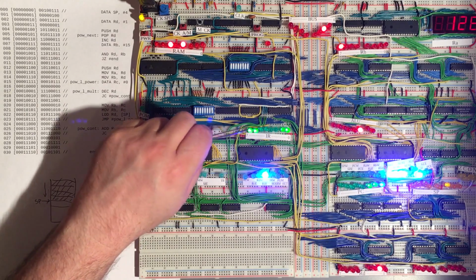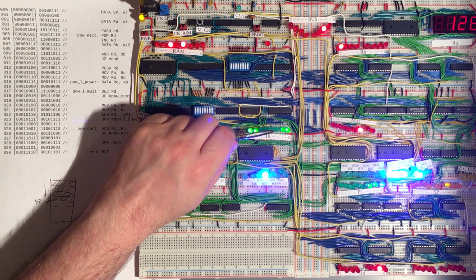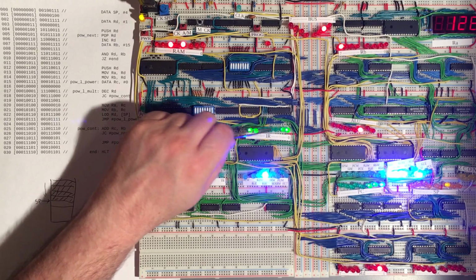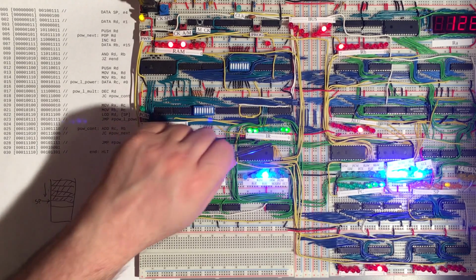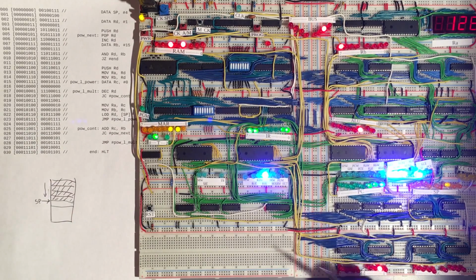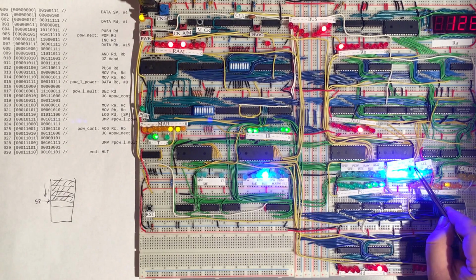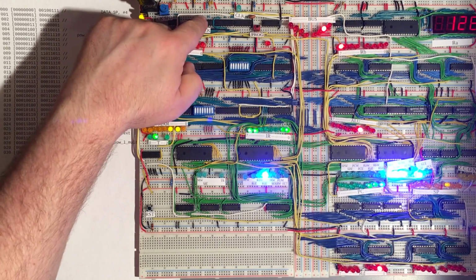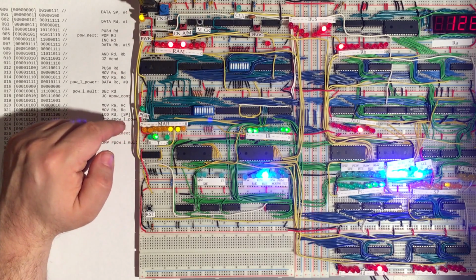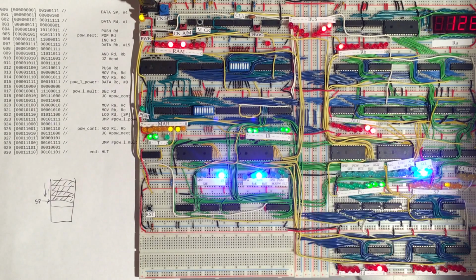So it's a 1-1, that means it's an ALU opcode without taking into account the carry, and this is this special value 000, which we've assigned to the increase operation, and we'll be performing it on the D register, which is value 1-1. So right, D register is being enabled, then our ALU once again is being set to increase, so we have the carry on, but we don't have the B input on, and we're using the A plus B operation, 0-1-1. We'll write it into the ALU register, and that will then write a 3 in there, and then that 3 will go out onto the bus and into the D register with this D write, and that will be the end of the increase instruction.